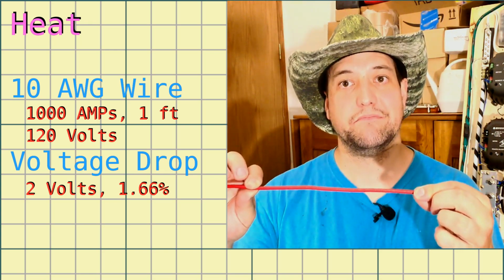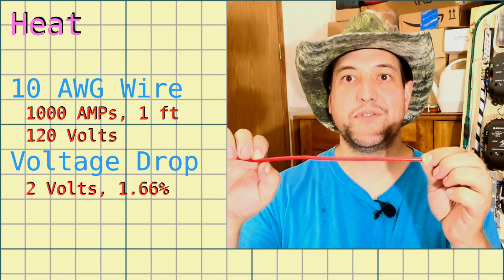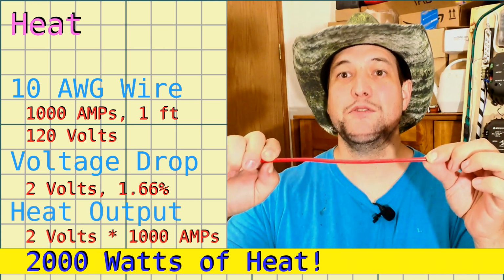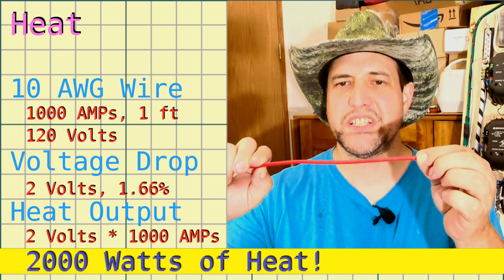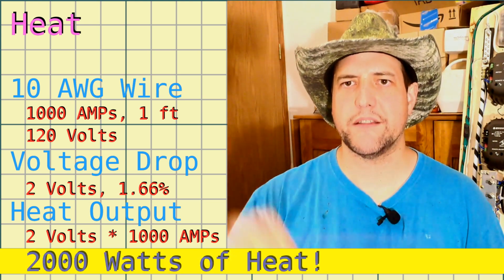Well, not really. See, the loss is actually, surprisingly, 2 volts. Oh yeah. So that means you've got 1.6% loss. That's not bad, right? Well, like I said, it goes into heat. So this wire, 1 foot long, you take the watts, so we take the voltage, 2 volts, times the amperage, 1000. This little wire is a 2000 watt heater. Whoa! As you can imagine, this will get glowing red hot, probably melt, burn everything off, and start a horrific fire. This is why you do not run 1000 amps down wire this size.